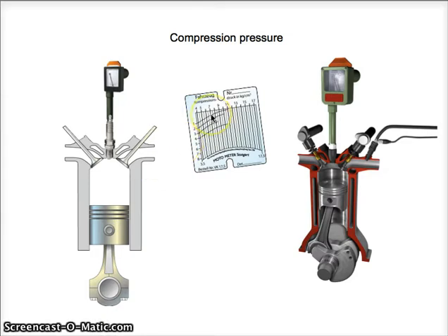Here you could see measurements for a 4-cylinder engine, and you see here this one has that compression pressure, and here you see cylinder 3 has a very different compression pressure, and that indicates that something is wrong in the engine. And it's very important to keep in mind that the compression pressure and the compression ratio are not exactly related to each other.